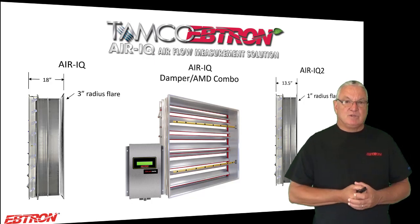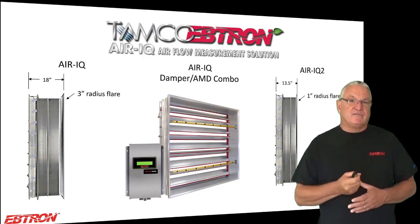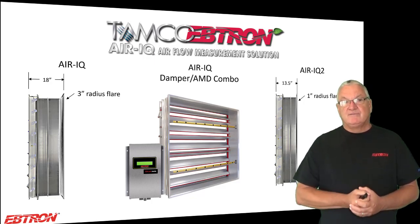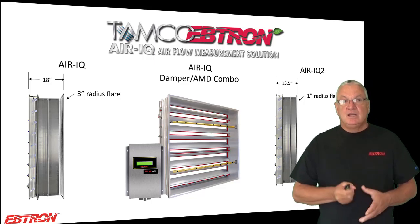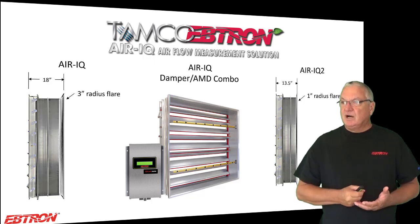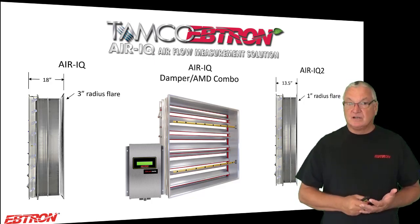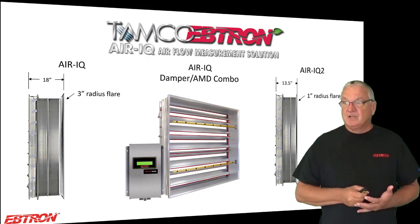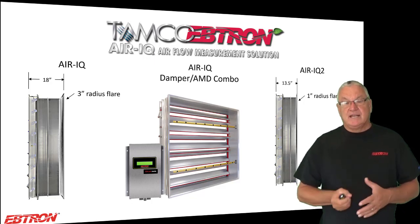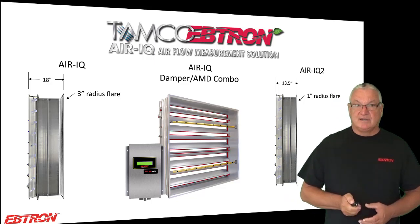We also package it with the Tamco damper. We call it the Air IQ or the Air IQ 2. There's a few little differences. The Air IQ is the original one. It's a little wider. It's got a bigger flare than the Air IQ 2. The Air IQ 1 is really something we keep along. It's good for unducted, higher velocity applications such as unducted returns, maybe exhaust fans, relief fans. The Air IQ 2 is really the product that you would use on your outdoor air intakes.